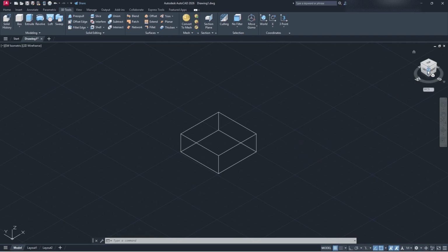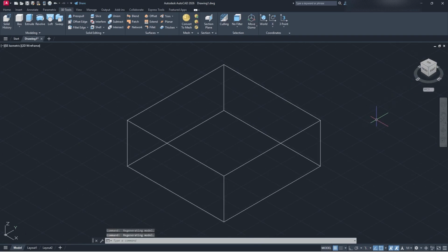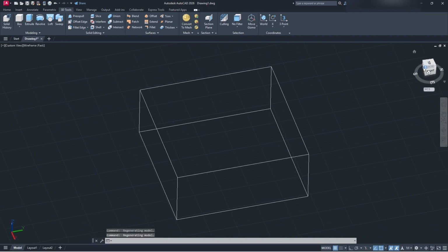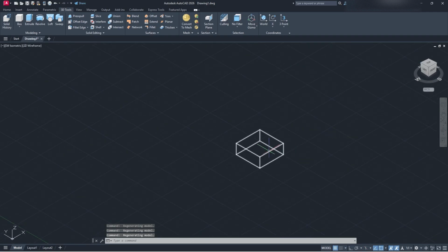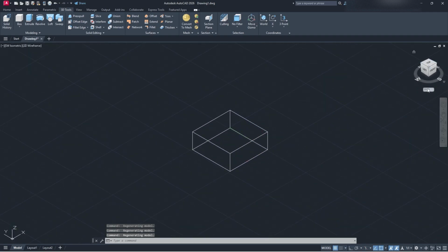I'm going to show you how to navigate around this for a minute. Usually when you're doing drawings in a three-dimensional space, I tend to use the bottom left-hand corner because it's just standard for what you usually use. You can also use the right-hand corner as well. It really depends on who you're working with, what you're doing, and what you're trying to figure out in AutoCAD. You can also do the bottom right corners. You can do just the sides like this, but that's less 3D. If you do the corners, that's the most 3D you're going to get. You can zoom in and out, and it's just easier to see at these angles. So you can go play around with that and figure out how you like using it.